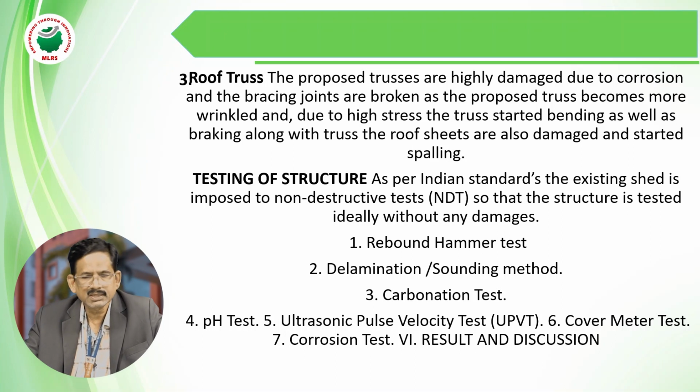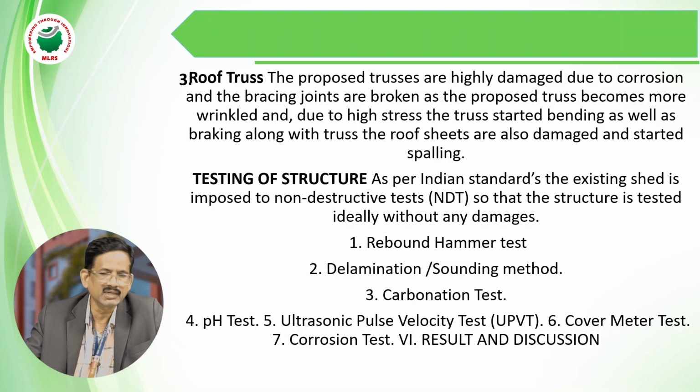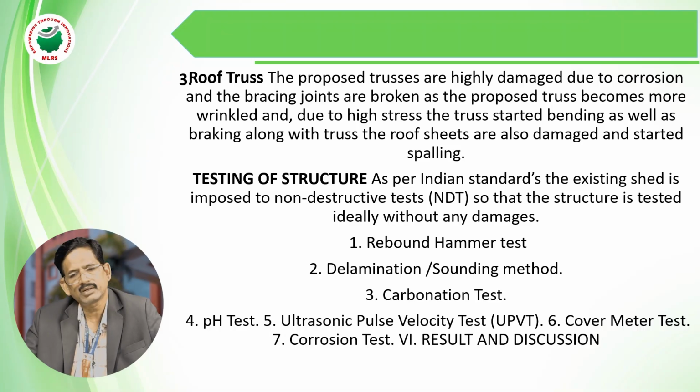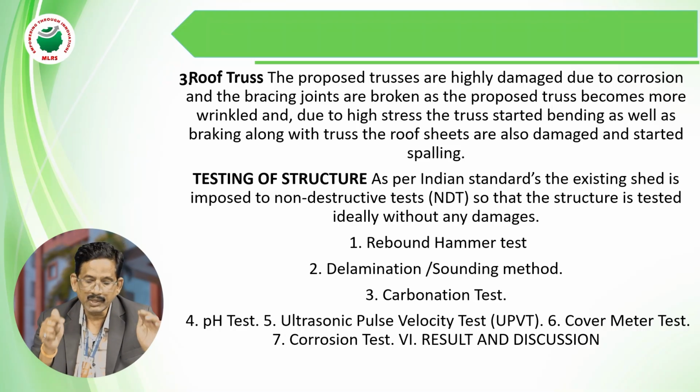parking purposes, instead of RCC buildings, we provide trusses. In factories and industries also, we don't want to go for RCC buildings. The cost will be more, and it is also not suitable for factories and the erection of machines. If you see in our Hyderabad, in the Balanagar, Jeedimetla area, so many trusses are there. In the trusses, we fix the machines, and there is a lot of fabrication work. For fabrication and industrial purposes, we go for trusses. This is also a truss member.